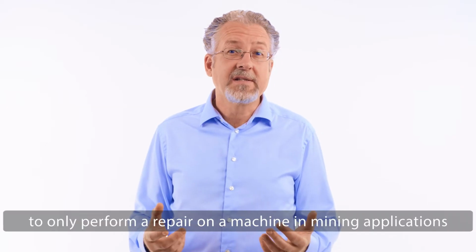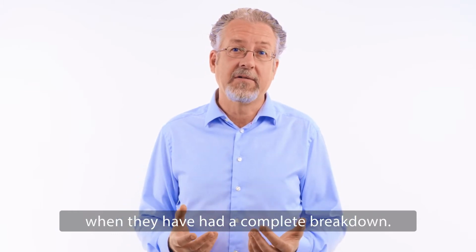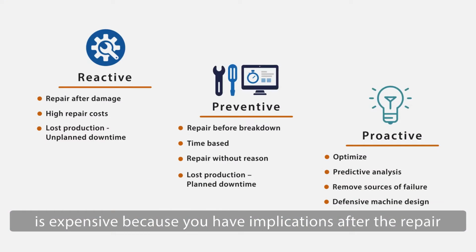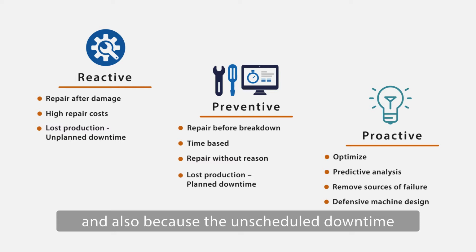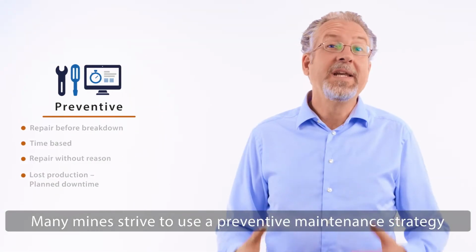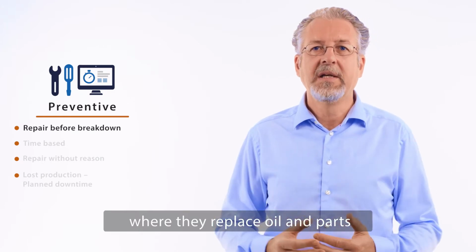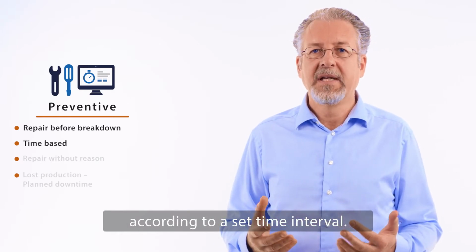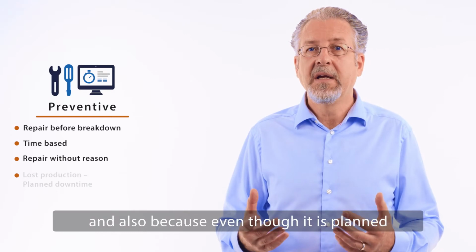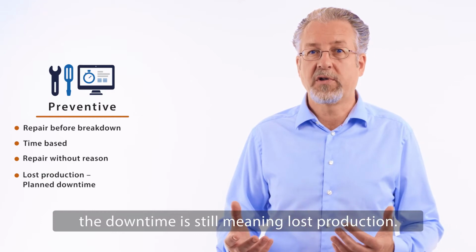It's not uncommon practice to only perform a repair on a machine in mining applications when they have had a complete breakdown. This reactive strategy is very expensive because you have implications after the repair and also because the unscheduled downtime will mean lost production. So many mines strive to use a preventive maintenance strategy where they replace oil and parts according to a set time interval. This may still be costly because the parts that are changed may not need to be, and also because even though it's planned, the downtime is still meaning lost production.